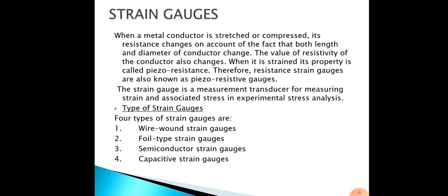The next one is the strain gauge. In a strain gauge, when the metal conductor is either stretched or compressed, its resistance will change, because both the length and diameter change, so the resistivity of the conductor also changes.